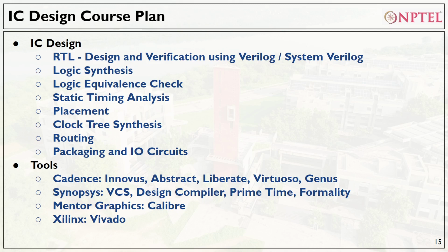Once you ensure all of this, you go to the back end of the design. You have designed some cells like AND gates, OR gates, or whatever. You have to make the layout of it, place each of them, and connect them. So this comes under placement and routing.